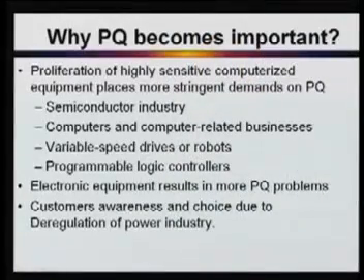Harmonics, as I said, are another sort of PQ problem. Harmonics may be of different orders, lower order or higher order, and they may cause transformer and neutral conductor heating, leading to reduced equipment lifespan, audio hum, power supply failures, overheating of motor loads, mal-operation of relays, and insulation breakdown.